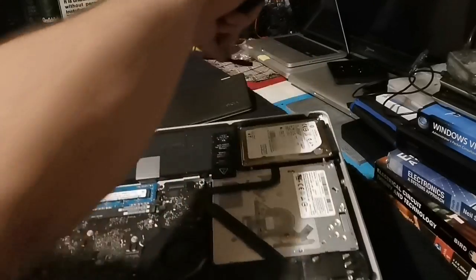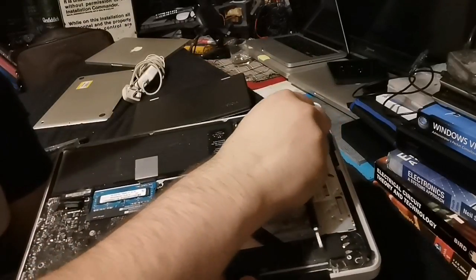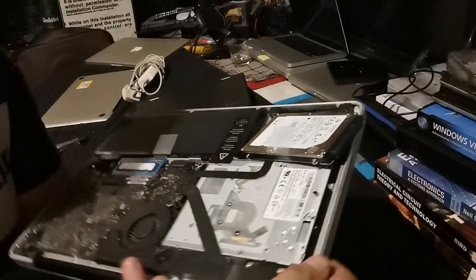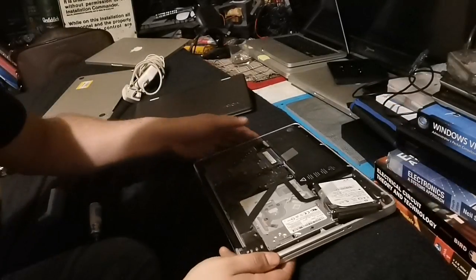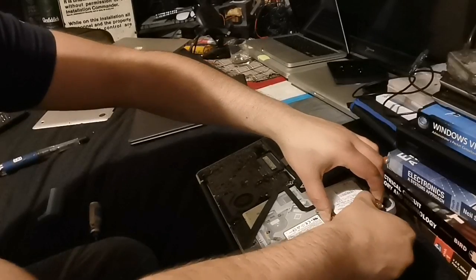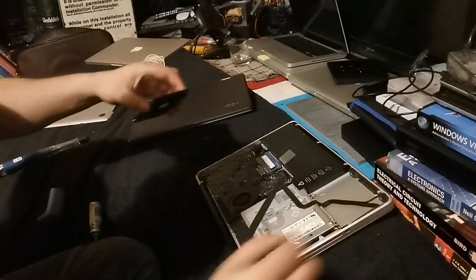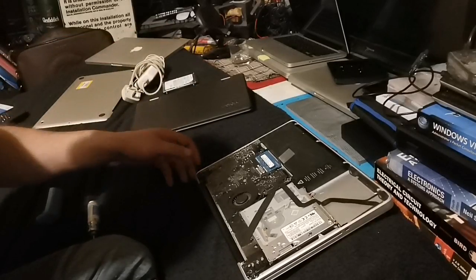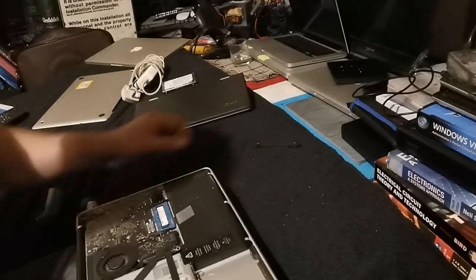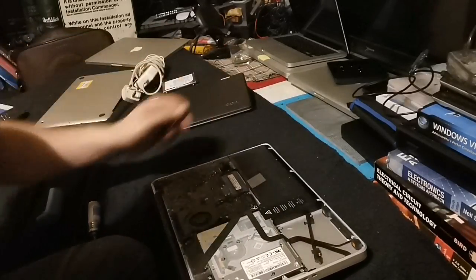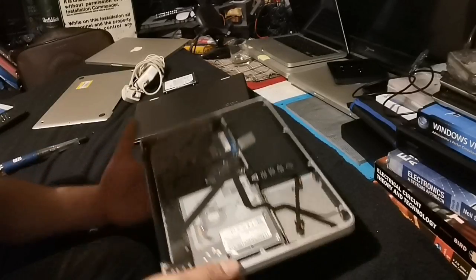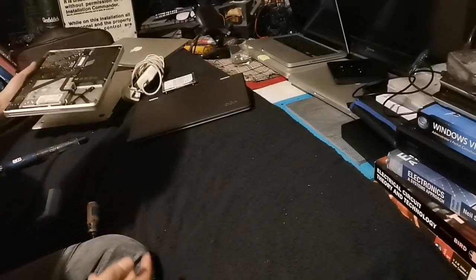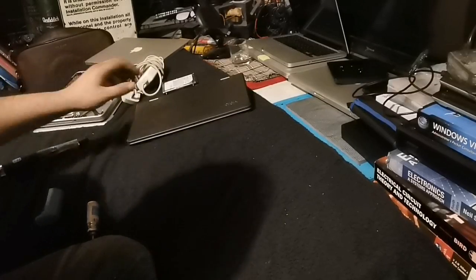Take out that top bar and set that to one side. Slide the drive out. At the back there's a ribbon. All you do, really this easy, disconnect it, like that. Set the drive off to one side. Make sure that you don't lose those. Make sure that you leave the other screws in there. Set this off to one side.